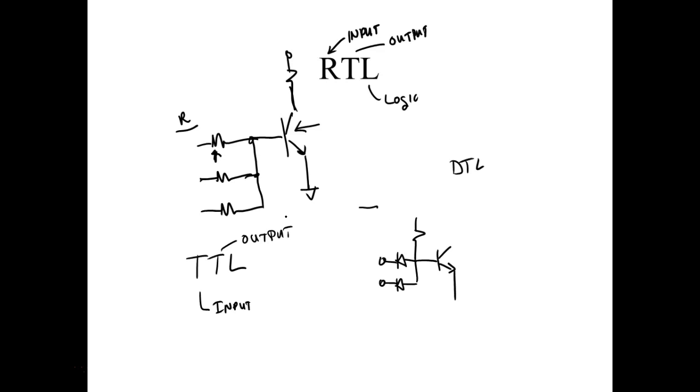So what determines the size of a transistor? How much current you're trying to control. So that means if I can get down to a circuit that requires very, very little current, then these devices can get extremely small, right? You understand? Well, digital can't control a lot of current. On TTL, the maximum on most TTL gates is only like 16 milliamps.